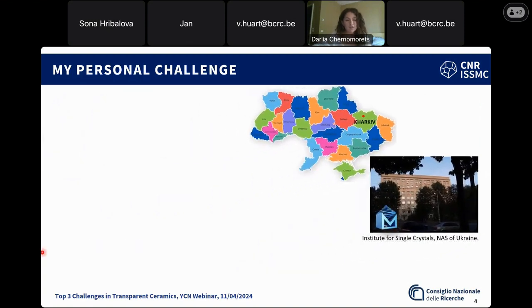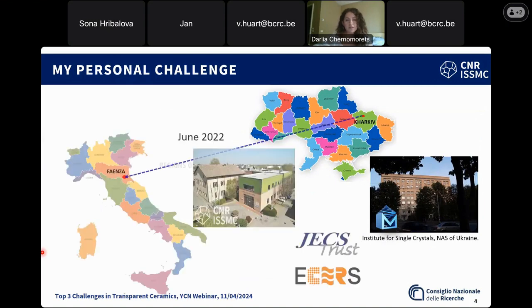And a manual test extrusion was performed, and we can see that in the first case with 72% of solid loading, viscosity is too low, and this ink is not printable at all, while the second one is quite promising, and in general it exhibits quite good properties at this stage.